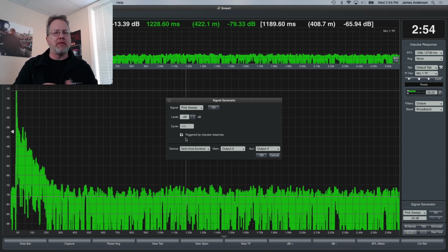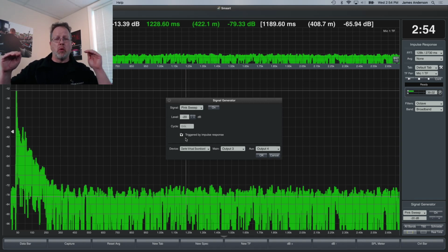We've got some level of harmonic distortion, nonlinearities in the system, and in some systems driven very hard, that could be a significant amount of harmonic distortion. And so the 1K that came out of the system was predominantly caused by the 1K that went into the system, but it was also caused when 500 cycles went into the system, and when 250, and when 333. So the harmonic distortion caused by the lower frequencies is also part of that output of the system.